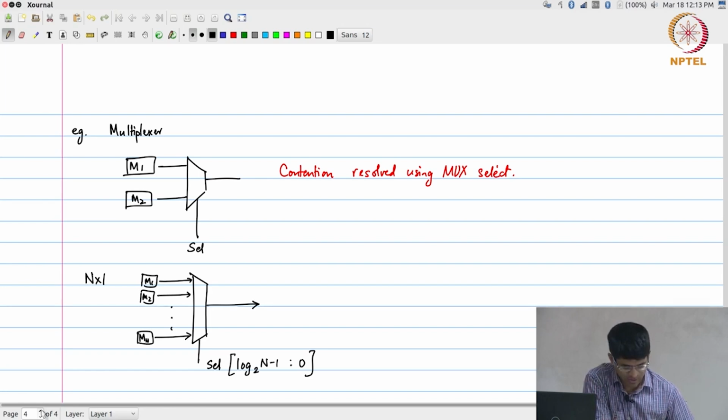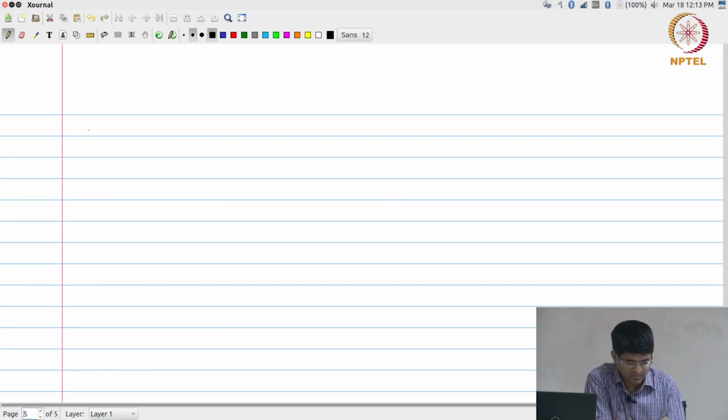Another approach that can be used is using so called tri-state logic, right. So, tri-state essentially deals with the fact that the transistors that are used in order to actually implement these logic gates, under certain conditions they can actually be made to behave like a high impedance terminal, right, meaning that for all practical purposes it is just disconnected from the rest of the circuit.